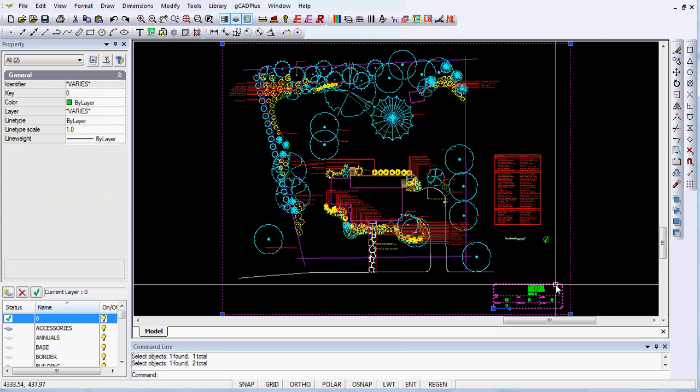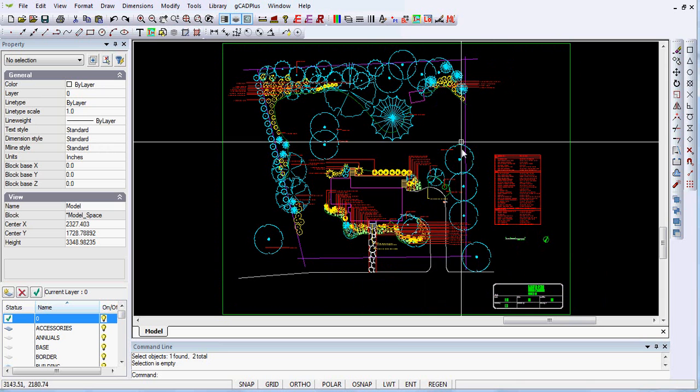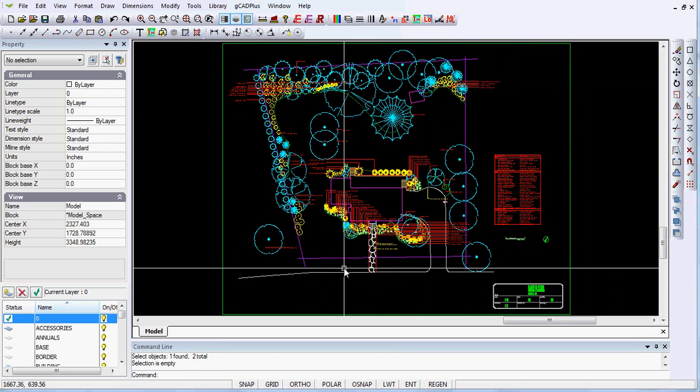Those things need to be copied into layout space and placed as, if you like, one-to-one in layout space, and then the drawing, the actual lines and entities that represent the site need to be scaled up by the appropriate factor, and that'll be 0.083 recurring, so we'll scale it up. So what I'll do now is try and shift the title block and the green border into layout space and do that scaling.